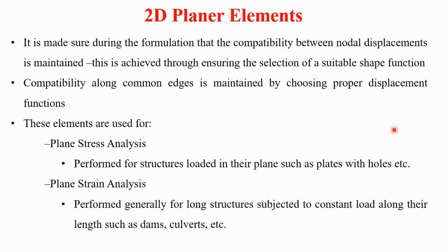For these 2D elements, it is made sure during the formulation that the compatibility between nodal displacements is maintained. This is achieved by selecting a suitable shape function, so that nodal displacement compatibility is obtained.